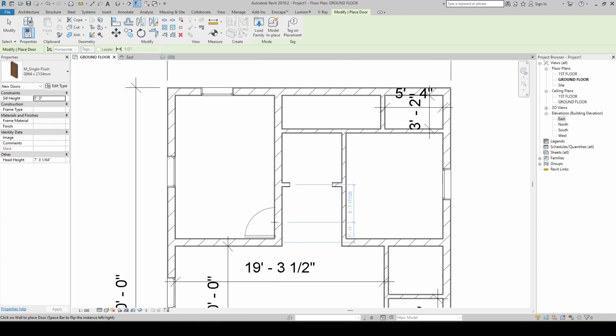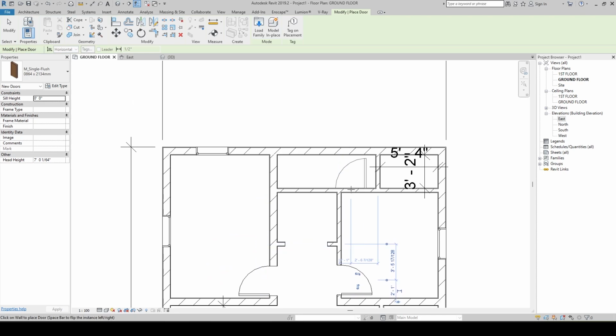So if you want to see, as of now, suppose you have selected the door and you hover the mouse around this particular area, the door swing is in the opposite direction. But if you want to change it towards the wall, you simply press the space bar. Once I press the space bar, the door swing changes towards the wall. Okay, now I simply click here as well, space, I have selected, the door has been changed. So here also I'll add this door, is fine.